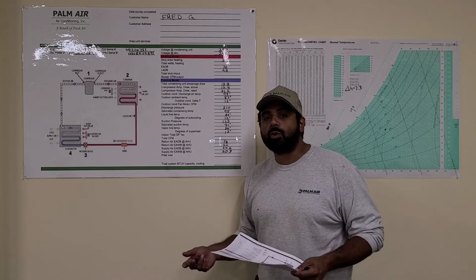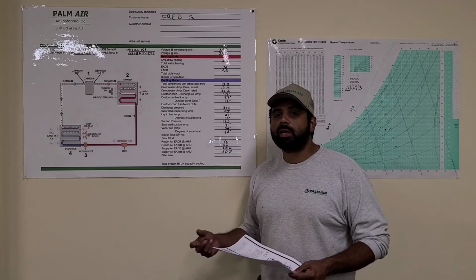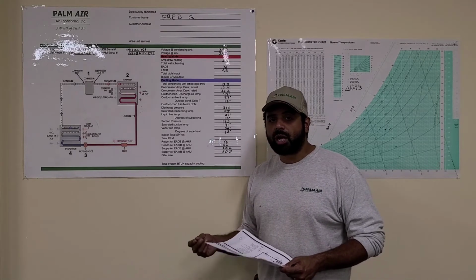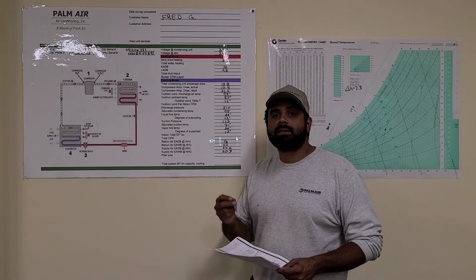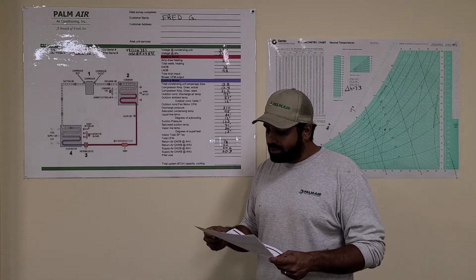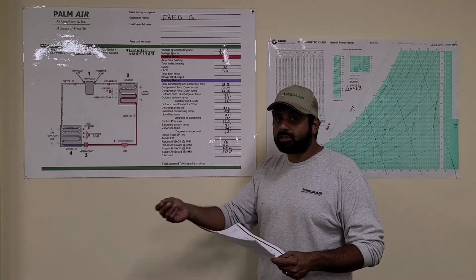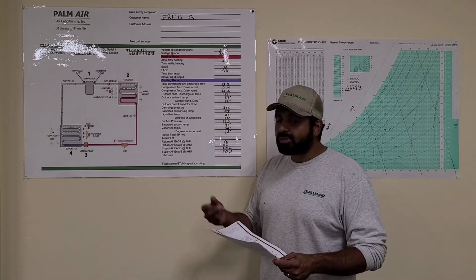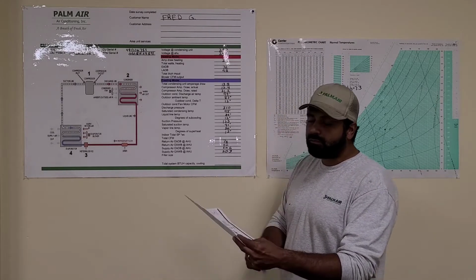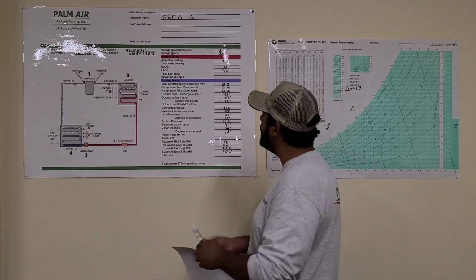And once again, I'm going to give you another constant. Anytime you want to come out with BTUs in heating, you're going to use 3.4 as your constant. You're going to take your watts times 3.4, and that's going to give you your BTU in heating. Watts, 9,633 in this case, times 3.4 comes out to be 32,752. I'm going to get those numbers written down.